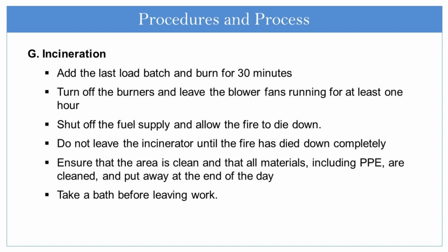After that, turn off the burners and leave the blower fans running for at least 1 hour. A double chamber incinerator runs at a temperature of 900 to 1200 degrees centigrade, so the blowers need to run for at least 1 hour to cool it down. Shut off the fuel supply and allow the fire to die down. Do not leave the incinerator until the fire has died down completely.